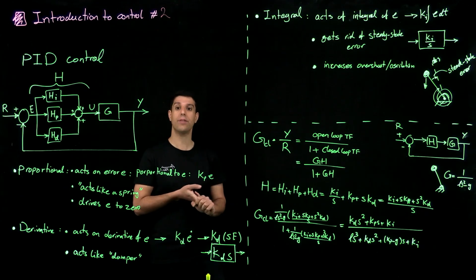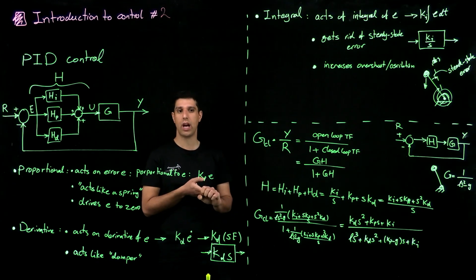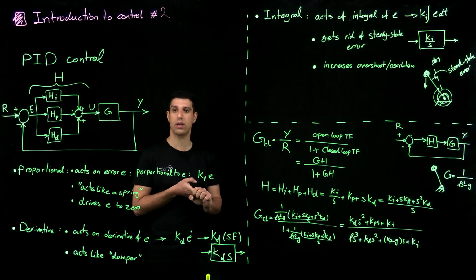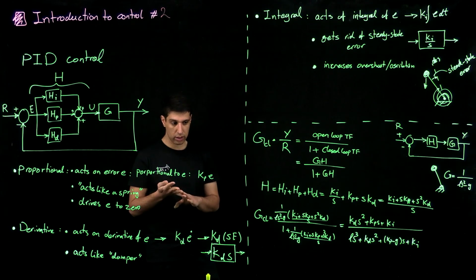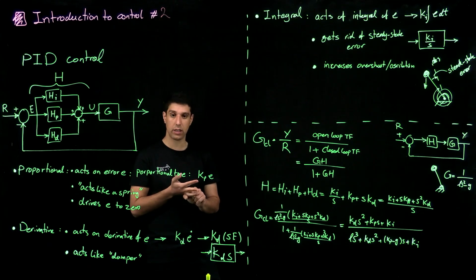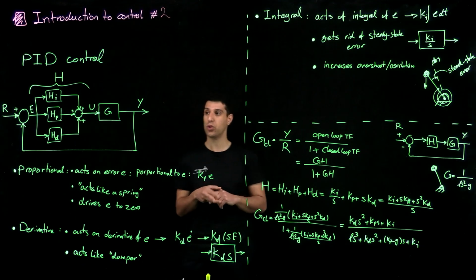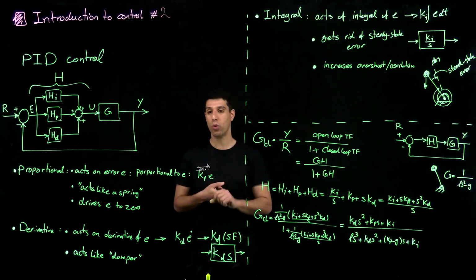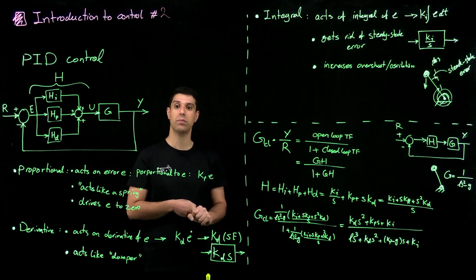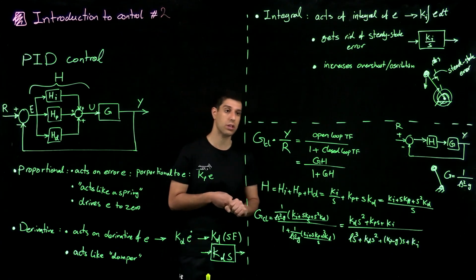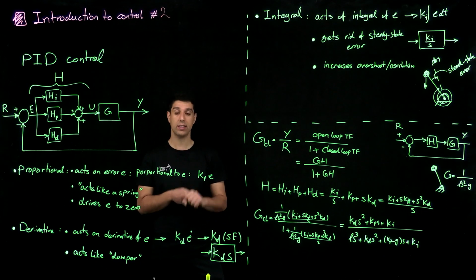We looked at frequencies, and mostly natural frequencies of multi-degree of freedom systems. And what else? Stability. Did I mention the stability? And we also looked at the stability, which coincidentally, the poles of the transfer function and the eigenvalues of a state space system are the same. And we could study stability of the system using that.